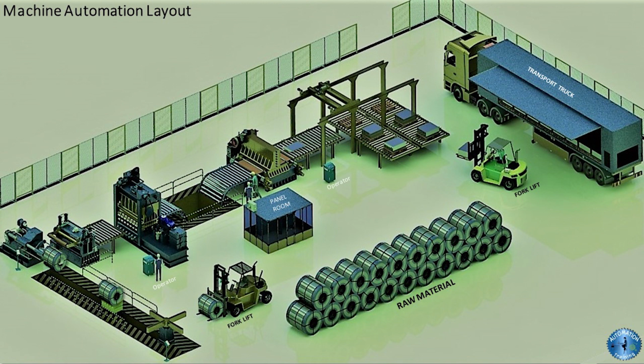Every machine has three main parts, like our computer, and those are input, processing and output. In the machine, a coil is the input, the section where it gets cut can be treated as processing, and the stacker section, such as cut sheets, can be the output of the machine. The machine is manufactured with various assemblies such as coil car, unwinder, pinching, leveler section, loop section, feeder section, shearing section, and stacking section with conveyor.